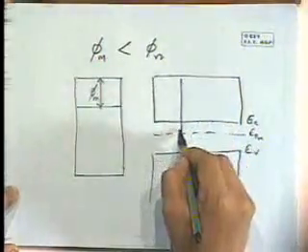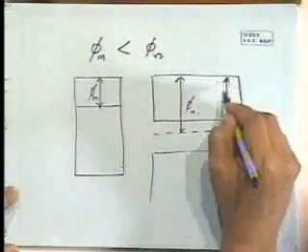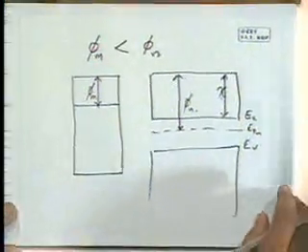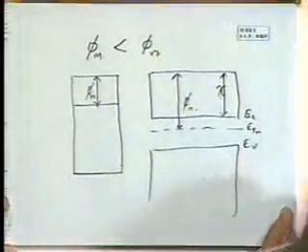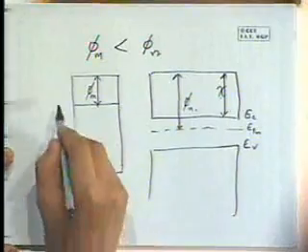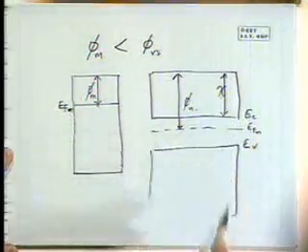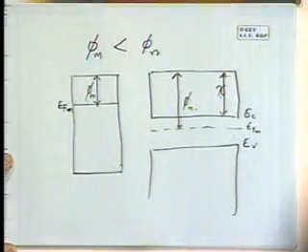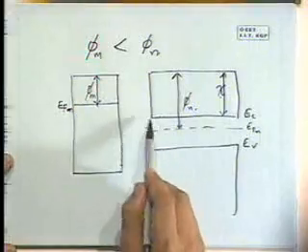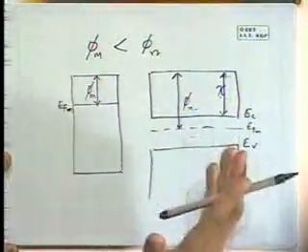So this is phi n then, and chi as before is here. And when we bring these two together, just as we did in the earlier case, electrons will flow from the metal to the semiconductor, and electrons will accumulate in here, and gradually it will start opposing the further flow.